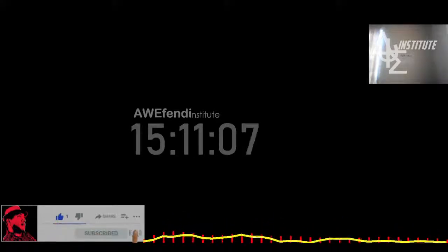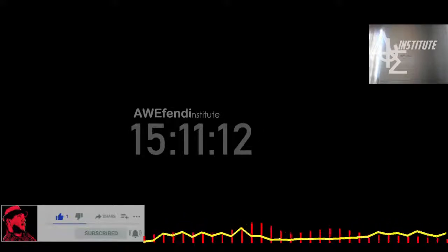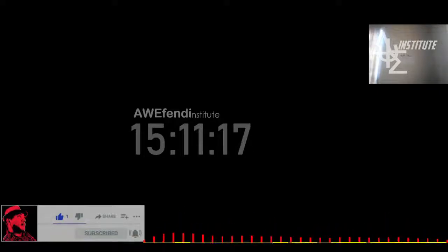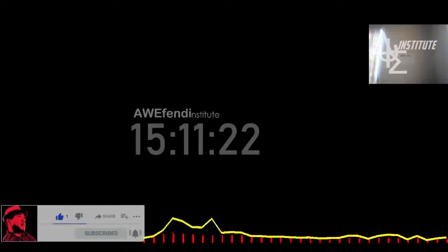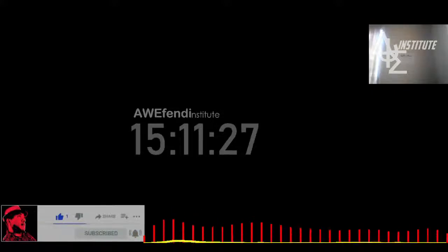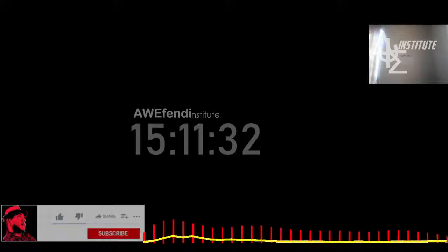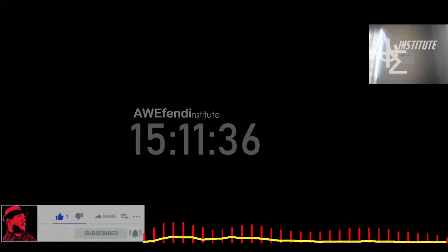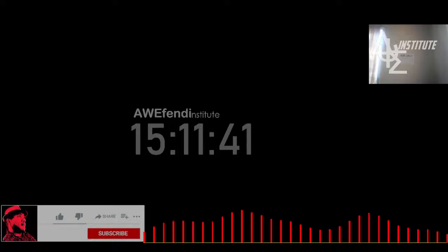You can see the relationship between your parameter and basically anything that you have in your monitors. So here you can see, increasing, of course, the flow on inlet 1, what is it going to do? It's going to push up this hot flow a little bit higher, contain it to a higher region on this outlet section of the piping. Good. So we can go back to the slides. That was the first demo.